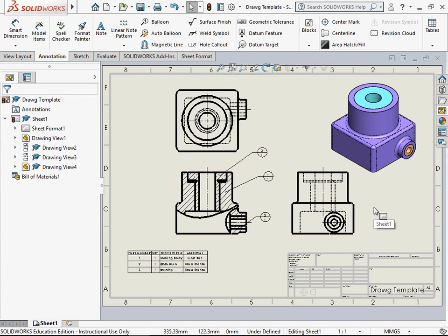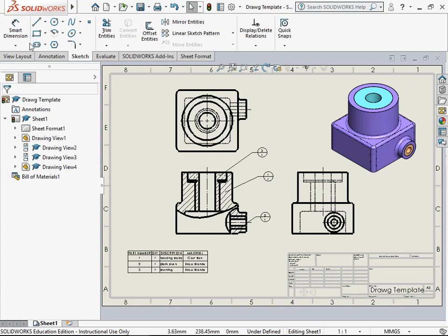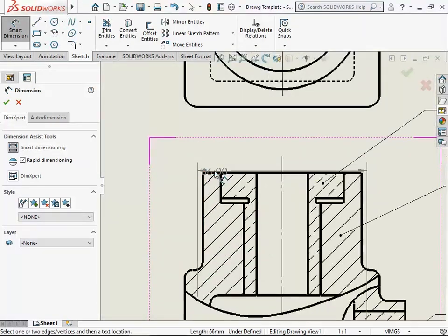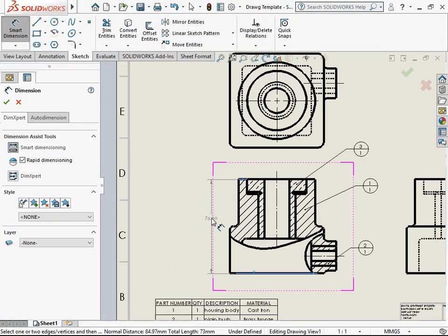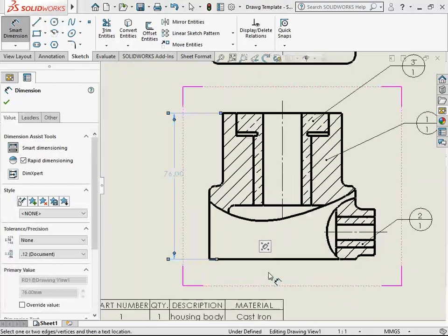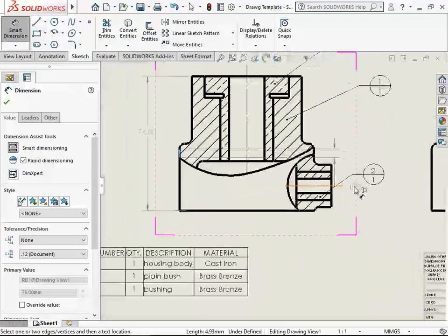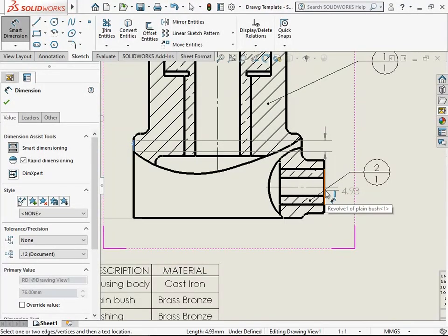As far as the dimensions are concerned, in an assembly view or assembly drawing file, we include the maximum dimensions. So let's go to sketch, dimension, sketch toolbar, you have smart dimension, pick up the bottom edge and the top edge to assign the overall height of the assembly. You have the edge on the left, edge on the right, giving you the overall width of the assembly.